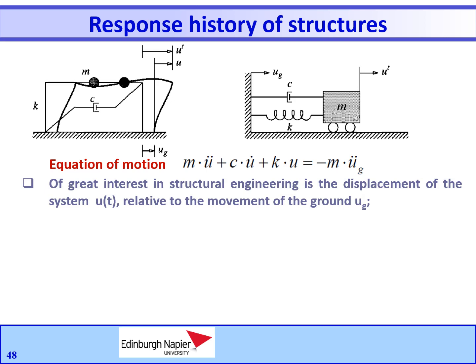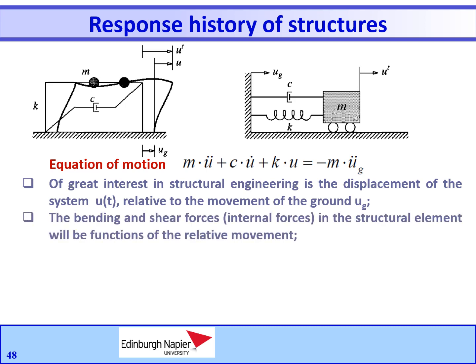Of great interest in structural engineering is the deformation of the system, or the displacement of the mass relative to the moving ground, to which the internal forces are linearly related. Why are we interested in the internal forces? These are the bending and shear forces in the structural element that will actually determine its design.